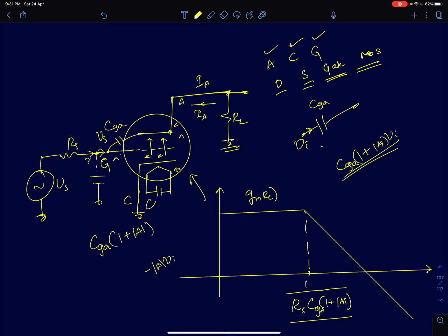Now just to quickly refresh your memory, the basic principle of operation of a vacuum tube amplifier is as follows: the cathode terminal is heated sufficiently, and when it is heated, it starts emitting electrons. So we have a cloud of electrons formed above the cathode terminal. This process is called thermionic emission, and these electrons will be drawn towards another plate called the anode if the voltage at the anode plate is greater than at the cathode plate. When these electrons reach the anode terminal, we have a current flowing from anode to cathode. I have written this current as IA, called the anode current.